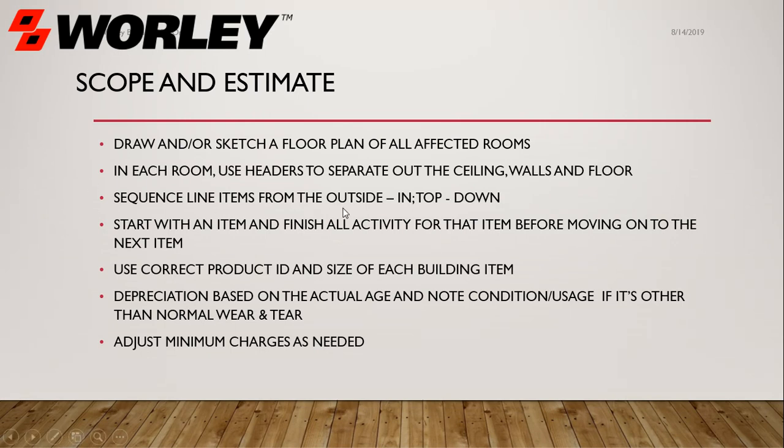Follow a sequence. Whether you're going outside in or top down, make sure you don't just start firing off photos, but use common sense. If the water discharges from the floor and it went up, start from the floor. Don't take an overview of the ceiling and then go to the floor. Start where the water started and then work your way to where the water went. I think it's a good practice.